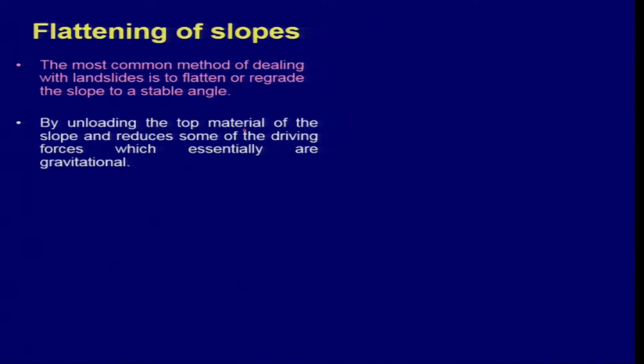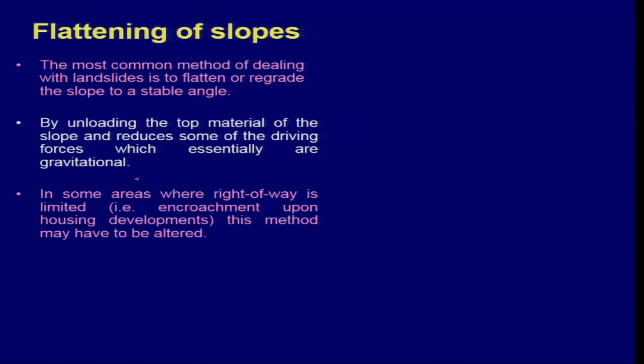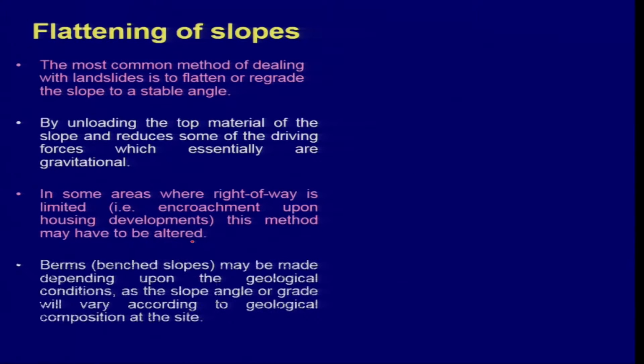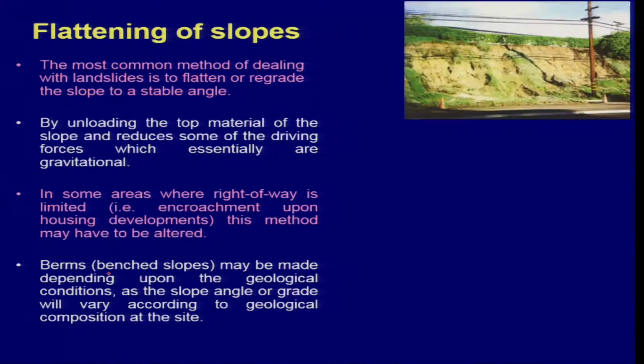By unloading the top material of the slope, you reduce some of the driving forces, which essentially are gravitational. In some areas where right of way is limited, or where there is encroachment from housing development, these methods have been altered. So, what people have done is they have created bench slopes.